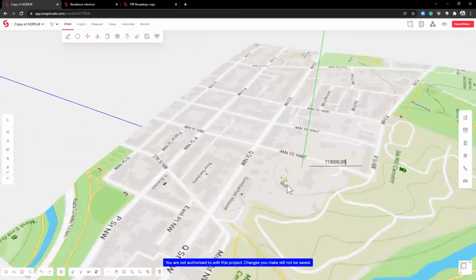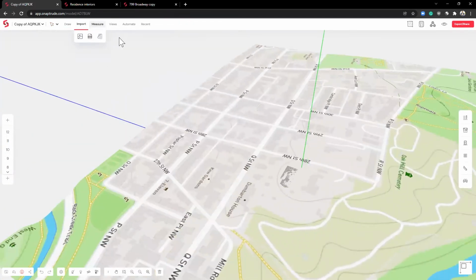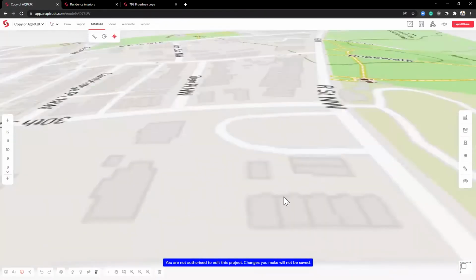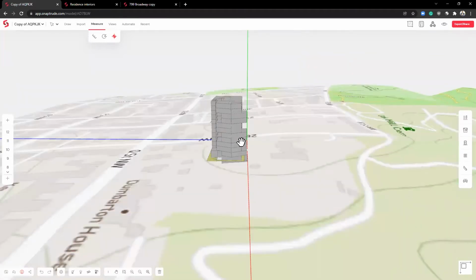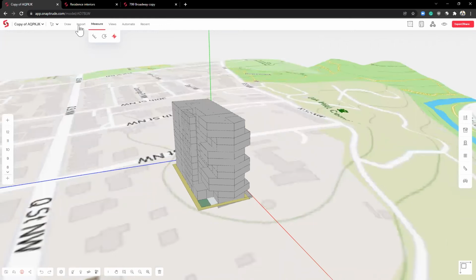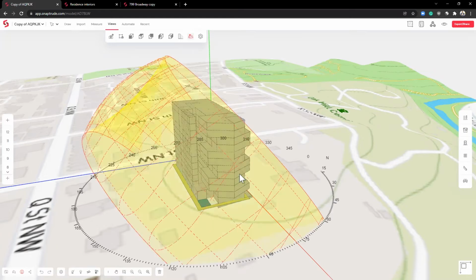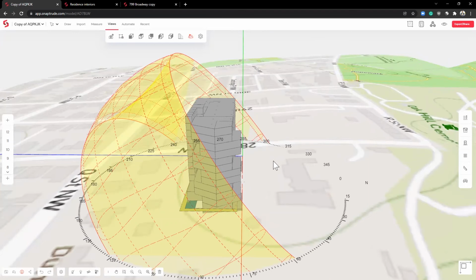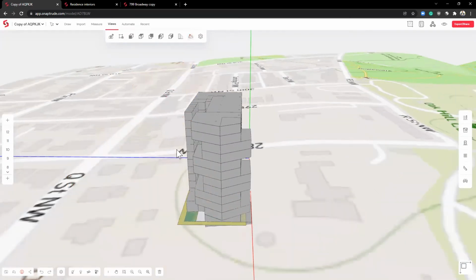So let me just navigate to the place which we had identified, and I can start setting the datum over here. And you can see how the space is over here, and figure out what is the best place to set the datum. And because it's subject to the latitude and longitude of that place, you can do localized climate studies, things like sun path diagram, which with a click of a button, you can generate that this is the true north. And this sun path diagram is generated for this latitude and longitude and not generally anything. And because of this localization, you can even bring up the neighborhood buildings, do shadow studies, etc., which I'll show you in a fairly more completed model very soon.